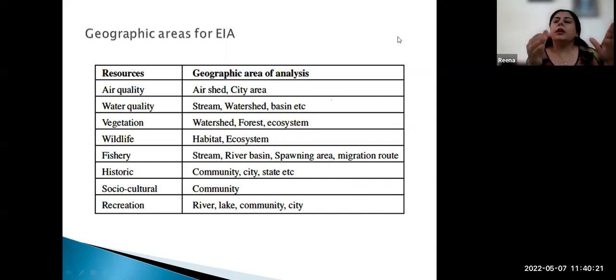I should ensure that, for example, if I am going to establish a landfill area, and in the east direction I have a habitation, a housing complex, then in the east direction I will not locate my main storage area for the project, because it will cause odor and pollution problems for the immediate housing complex. In that area, I can establish my office site, so that there is a buffer between the storage of the solid waste, the administrative office, and then the housing complex.